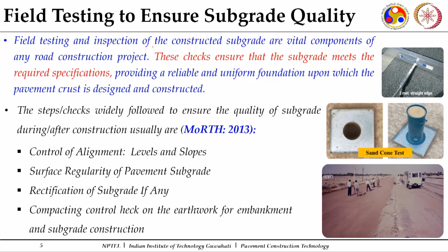So, field testing and inspection of the constructed subgrade are vital components of any road construction project. These checks ensure that the subgrade meets the required specifications which are laid by different codal standards, MORTH and IRC standards, providing a reliable and uniform foundation upon which the pavement crust is designed and constructed.